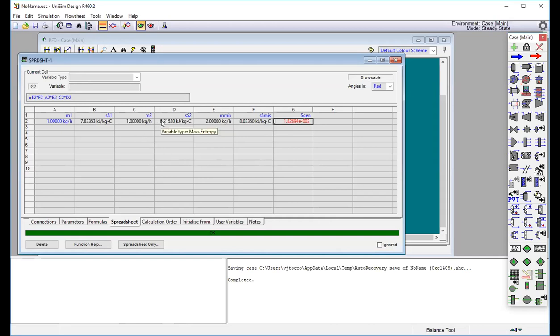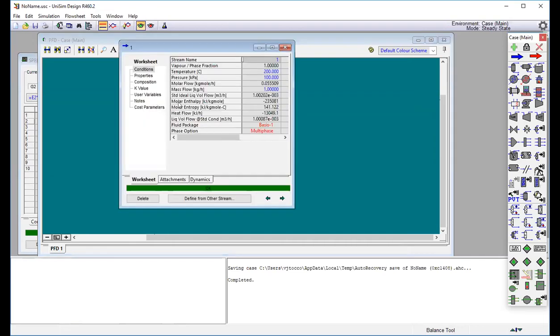Okay, one more thing I want to show you, and that is changing the significant digits that you get in your flow sheets. So I have set it to 6 significant figures. You probably have it set to 4 significant figures. It doesn't really matter. I'm a big believer in fewer significant figures for the most part because it makes things easier to read and contextualize and compare quickly. But sometimes you may want a larger degree of precision. And because the steam tables are so precise, the steam tables themselves go out to 5 sig figs, and I think UNISIM goes up to 6 sig figs.